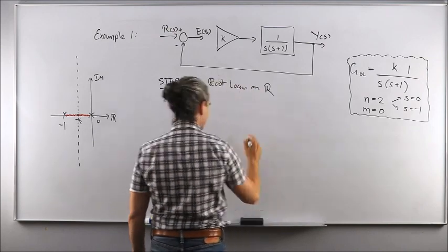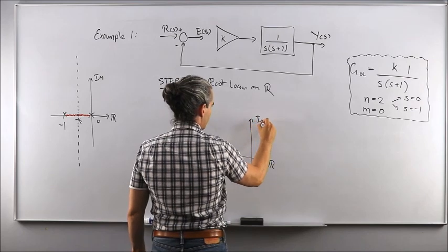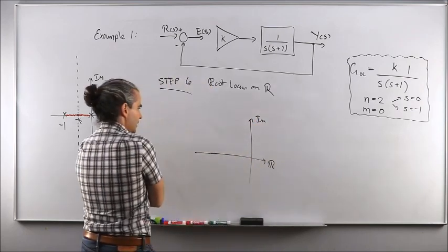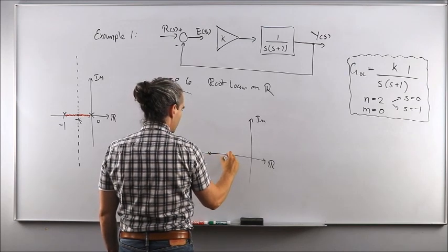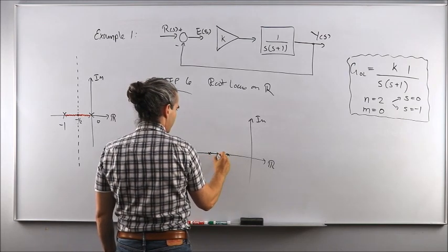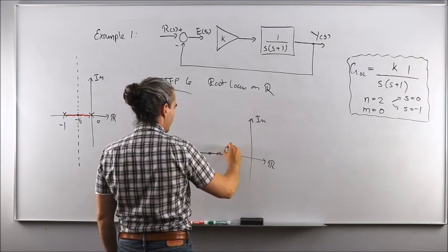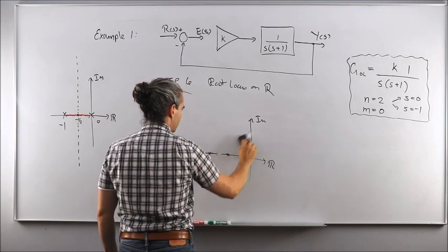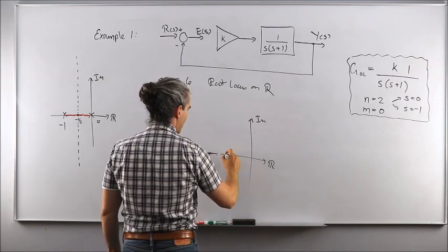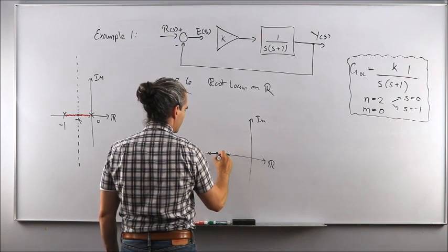If you end up with a complex root locus with a bunch of poles and zeros all over the place, sometimes two poles would fly towards each other, meet up, and instead of flying up and down, they would want to fly along asymptotes that may have an intersection different than where those two poles meet on the real axis.